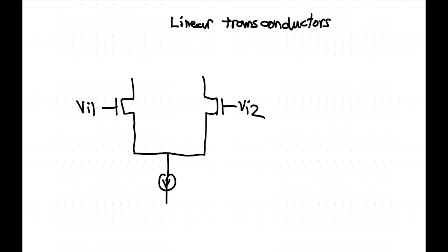So yeah, not linear. Now, the first thing you can do about that, the easiest thing, is to put in some source degeneration resistance. This is your go-to method for linearizing a circuit. So putting in some resistance here, get rid of some of these wires here, and then putting in some resistance here.